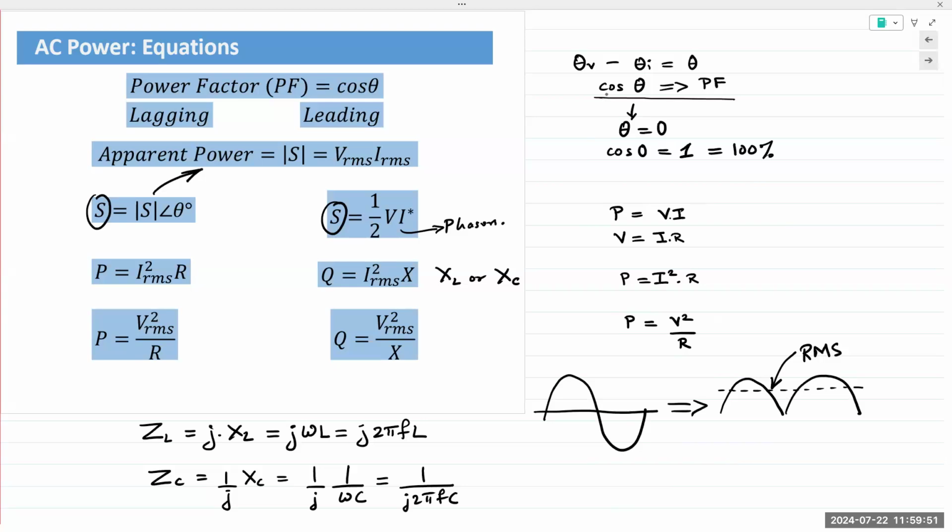It's not possible to get 0 because the speeds of the machine vary, how much the machine is utilized varies, the overall load of a system of a customer always varies. It's never constant, it's never fixed. Okay. So the goal is to get it as close to 0 as possible. So power factor is basically describing the reactive power requirement of a customer, of a system. And it's given by the cosine of the phase angle. Cosine of the power angle. We want that power angle to be as small as possible.